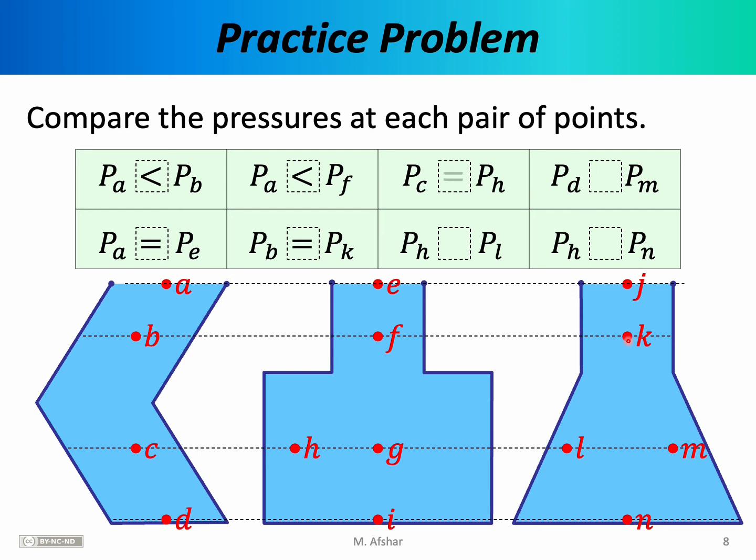The pressure at point C is also equal to the pressure at point H because once again point C and point H are at the same depth. Notice in all of these cases we're measuring the depth relative to the top of the fluid. In this example, all 3 fluids have the same top point. They have all been filled to exactly the same height.